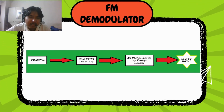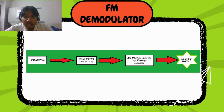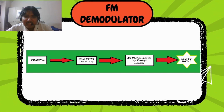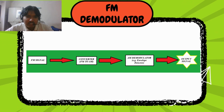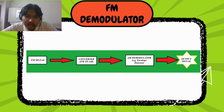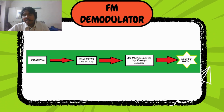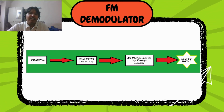Second, we have the FM demodulator. The FM demodulator can generate an AM signal whose amplitude is the same as the instantaneous frequency of the FM signal. So using an LTI system that has a frequency response that is approximately a straight line in the frequency band of the FM signal, the original message can be retrieved using an AM demodulator. For the AM demodulator, just like before, you can use an envelope detector.